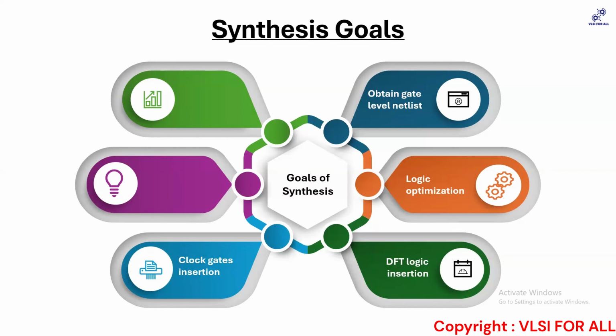Because if you look at dynamic power dissipation, it is alpha f C VDD square. Alpha is how much your gate activity is happening, f is the frequency of the clock, C is the capacitance, and VDD is the supply voltage. So I have to reduce this alpha. Don't switch it multiple times because I don't need it. My data is stable for at least 6 clocks. So this is something you define, and this is the way the tool understands and develops this logic and gives you an ICG cell, or call it a CGC. I can explain this in much more detail later when we go through it. Just for an overview, I gave it like this.